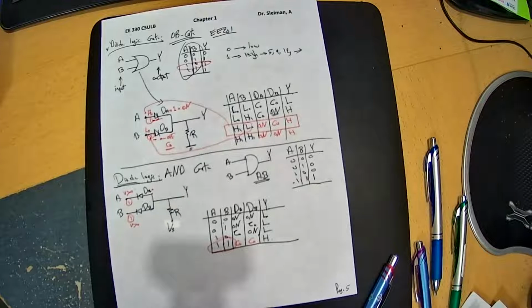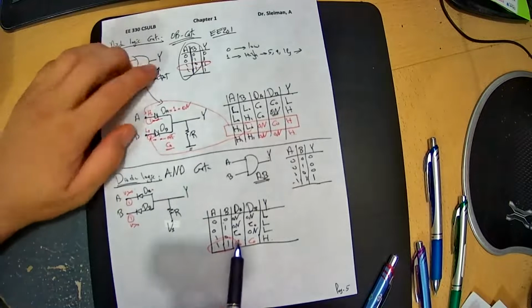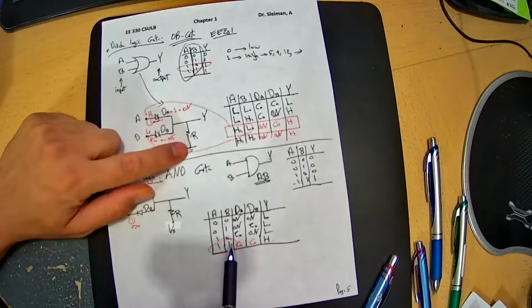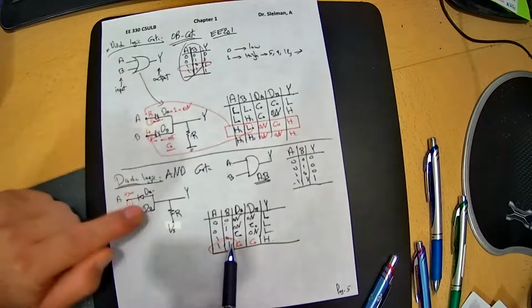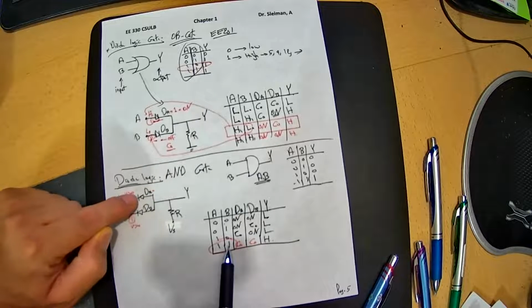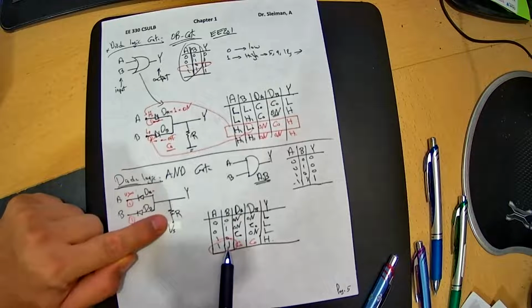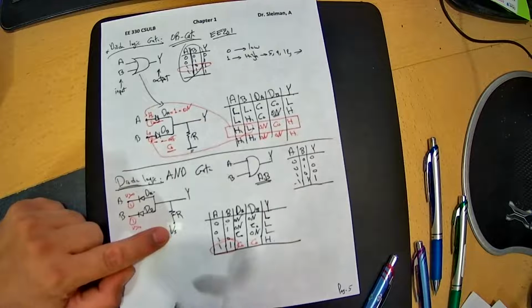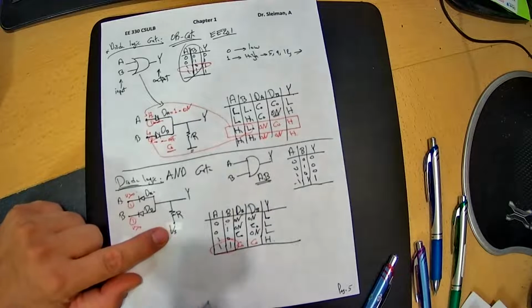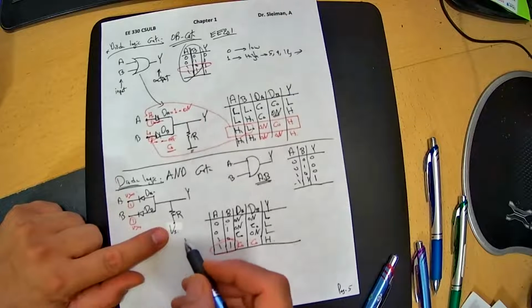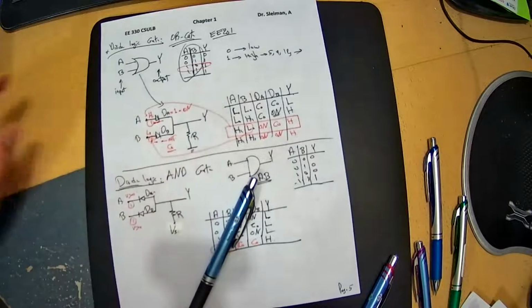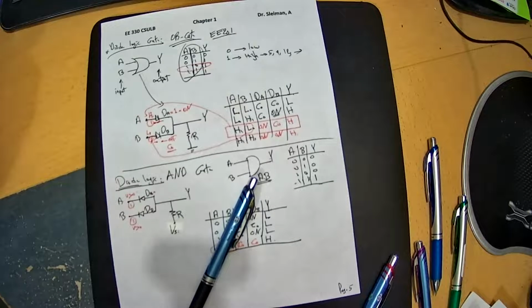I hope everybody understood. In the OR gate, we short the output through a resistor to the ground. In the AND gate, with reverse bias diodes, we short the output through the resistor to the voltage source. This could be 5 volts, or any voltage associated with the circuit.